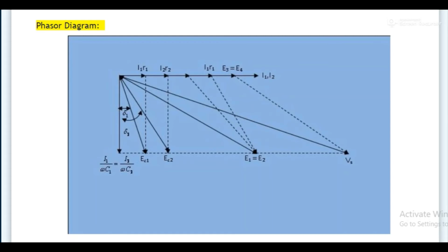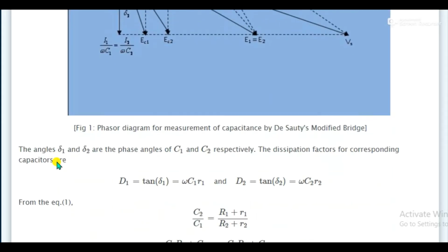You can have your own method of remembering this; if you remember it yourself, there is no need to get confused. This was my personal method, and you will never forget it. In a capacitor, the current leads the voltage, and in an inductor the opposite follows. Just following this rule, you can draw the phasor diagram if required.